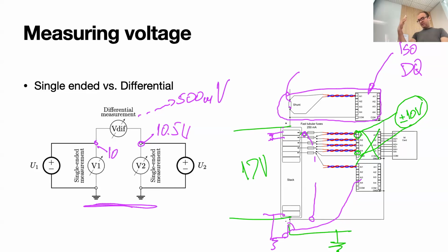But luckily, because here you have enough resources and there was one spare data acquisition card, we decided to be on a safe side, just in case somebody makes a positioning mistake, and put the shunt on its own data acquisition card. So even if the shunt is mounted on the plus side of the potential, nothing will break, because the maximum difference here will never exceed 20 volts.